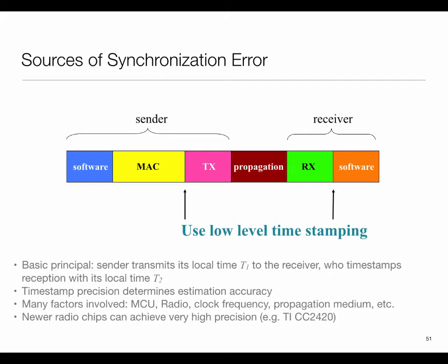In the sense that instead of reading the timer inside the interrupt handler, you let the hardware handle this. Almost any microcontroller nowadays will provide you with at least a couple of counters with this kind of capability. That is one of the ways you can get fine accuracy of time stamping, basically. So using these kinds of techniques, one can do things.